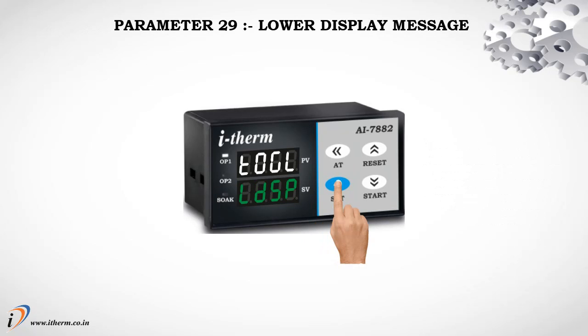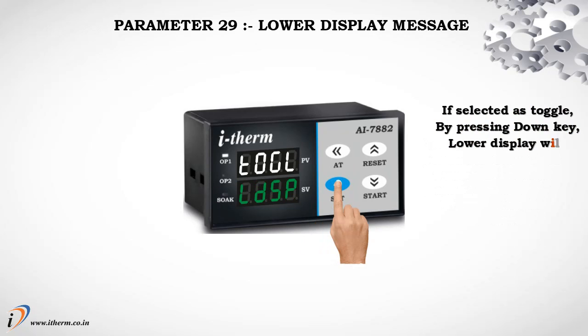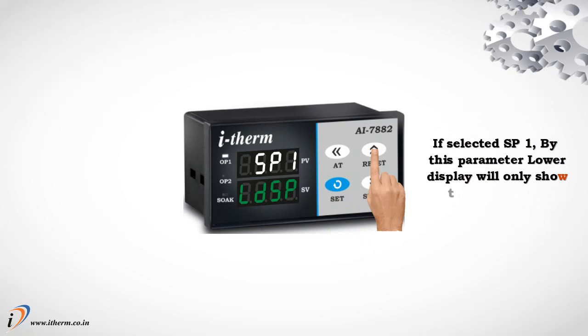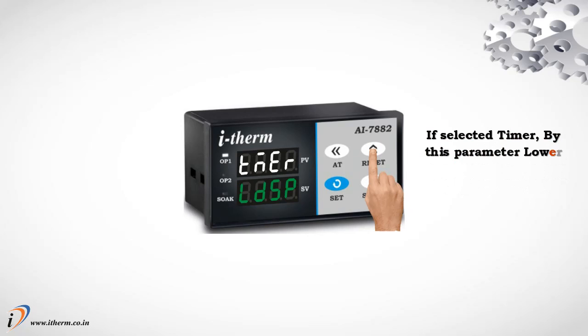Parameter 29, lower display message. If selected as toggle, by pressing down key, lower display will toggle between set point 1 value, set point 2 value, alarm set point value and timer value. If selected set point 1, by this parameter lower display will only show the set point 1 value. If selected timer, by this parameter lower display will only show the timer value.